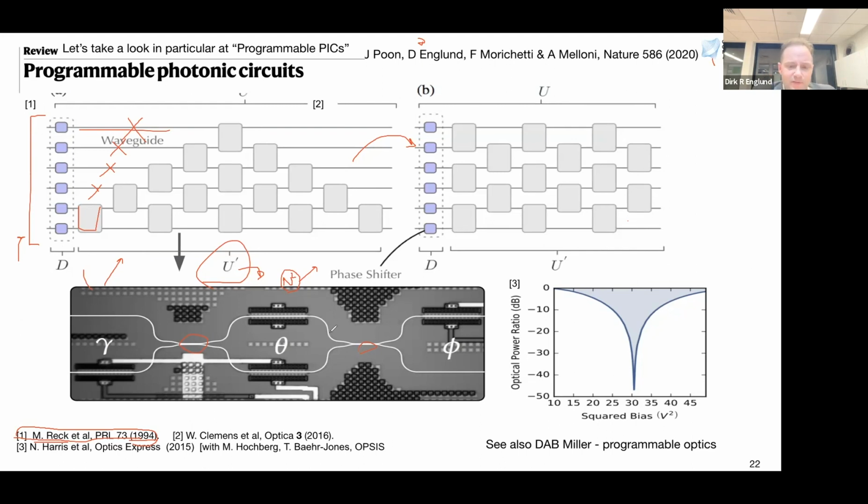And so it's been very important to us, and the community, to find ways of getting these beam splitters really, really close to 50-50. But again, the fab does the best that they can, but it might be 49-51. And if that's already going to reduce the fidelity in your transformation, you should think of other ways of doing that. And I'll show you in a moment how we have gotten around that by using some more clever algorithms that can compensate for pretty large beam splitter imbalances.